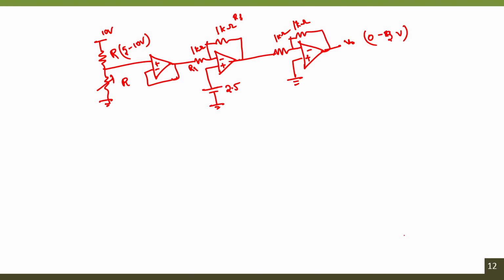Great. Of course, is this the only configuration that we can build? No, of course, there are different ways of doing this. This is one approach. Another approach would be optimizing the complete circuit. What I mean by optimization is the number of operational amplifiers, or the number of resources that we are using. Why do I have to consider this? Because when you say 2.5, the complete circuit is operating with 10 volts.